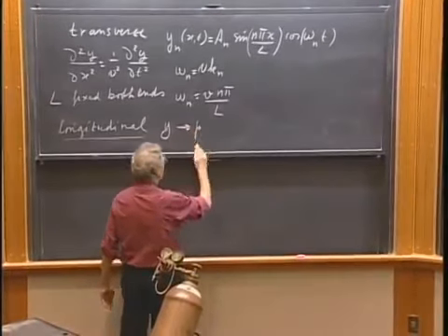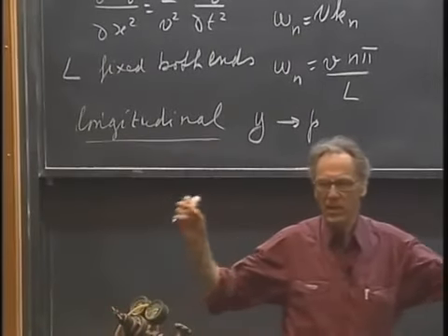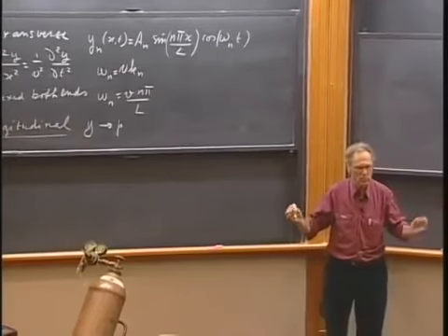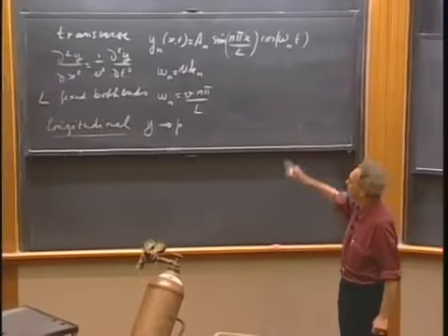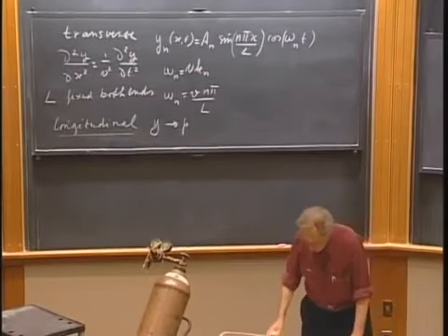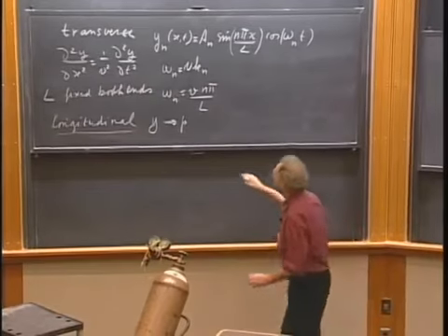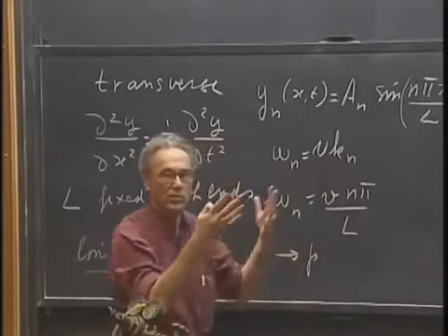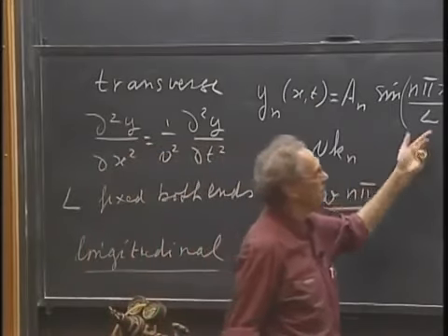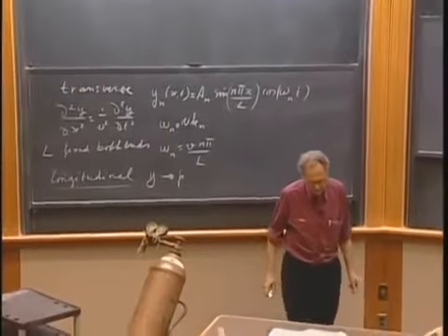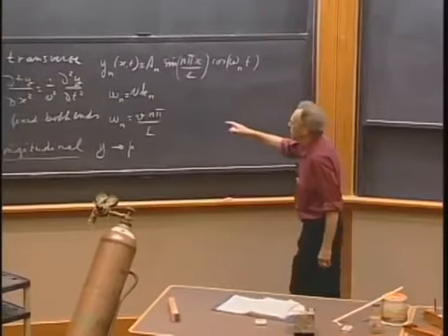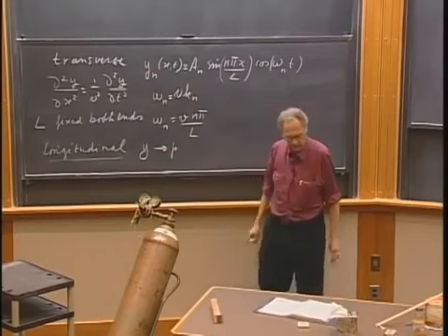p, p being the overpressure. Because at the ends of an open-open system, the pressure can never become higher or lower than ambient, and so you have pressure nodes. And so you get exactly the same solution that you have there, provided that you replace this by a p, and this you replace maybe by some capital P, which is then the amplitude. But this and this is the same, except, of course, that omega, this v is non-negotiable in the case of sound.